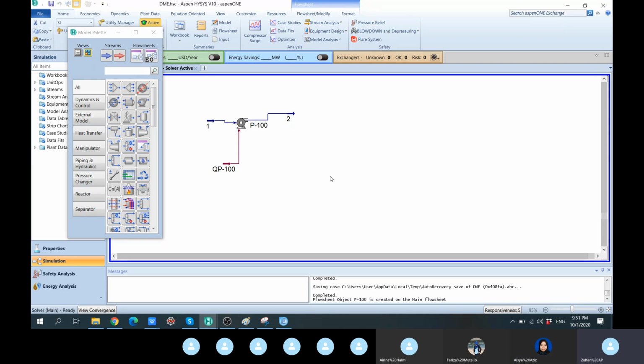If the temperature is too high, we have mechanical material limits in the compressor, the temperature limits on the seals. The upper limit allowed for that material is somewhere about 160, 170 degrees C, or maybe 180, depending on the mechanical seals that they use.